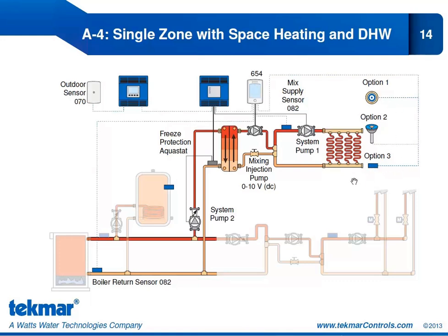I also want to draw your attention to this boiler return sensor. So in this application, we have chosen to do boiler protection. We are connecting the boiler return sensor to the 654. Now, if you remember, we'll see it on the following slide, but there is a shared terminal for the boiler return sensor and the outdoor sensor.